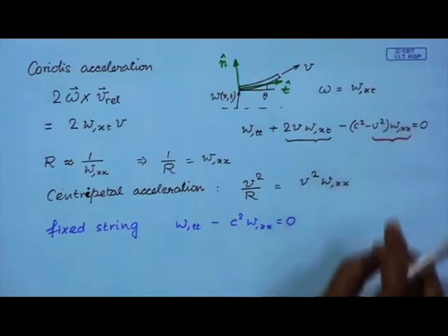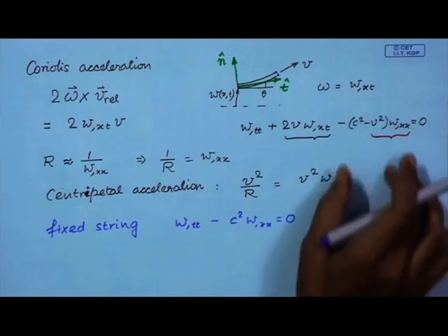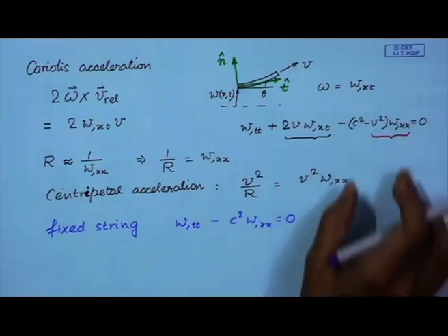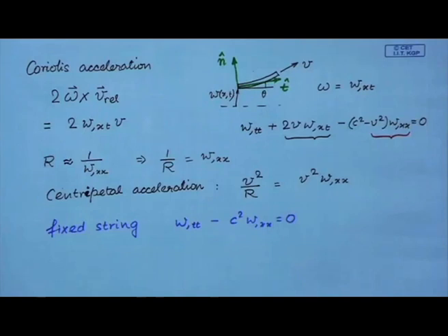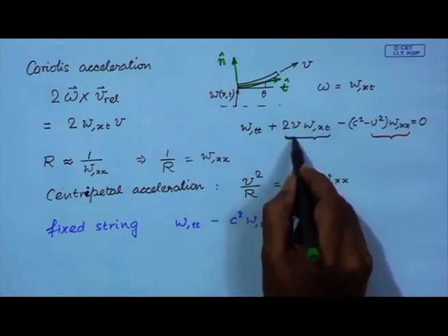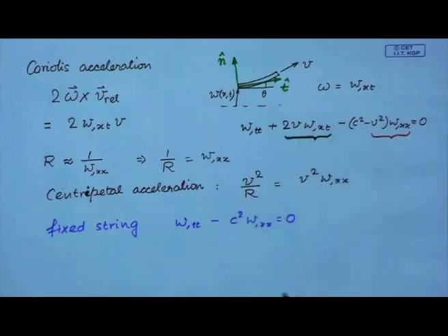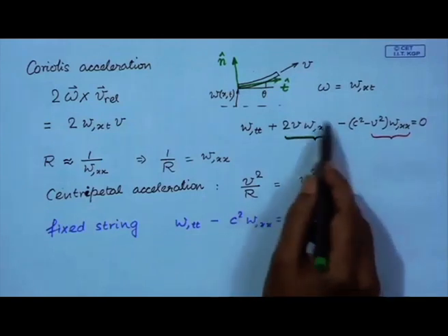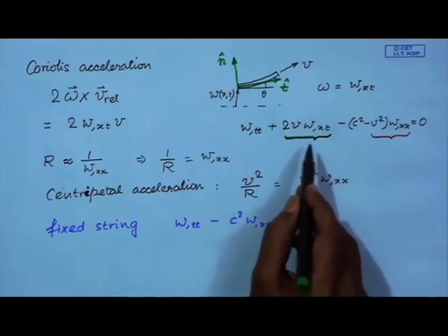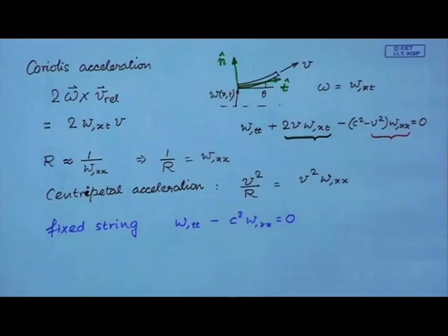So, in the event the velocity equals c, which is the speed of transverse waves in the string, then the string loses stiffness. So, this is an unusual behavior that we see in a translating string. The second thing is this term, the Coriolis acceleration term. This has a single time derivative. Now, when we discussed damping, normally we had in the damping terms a single time derivative. So, the question might arise whether this term is conservative or not.